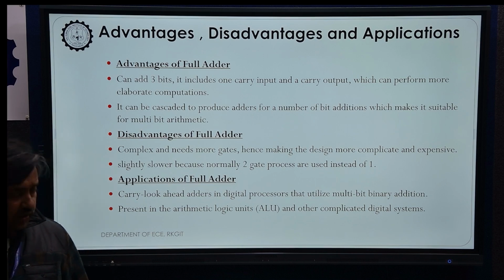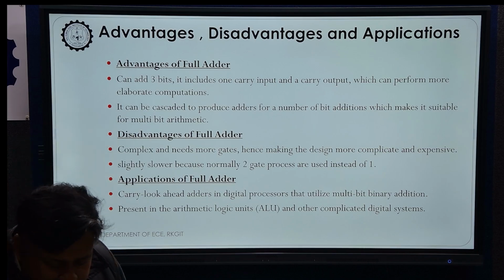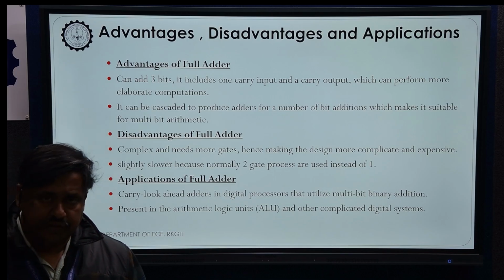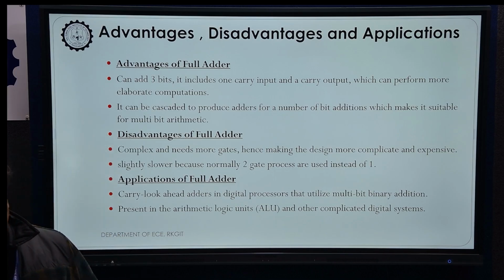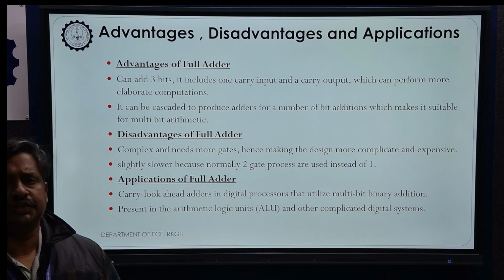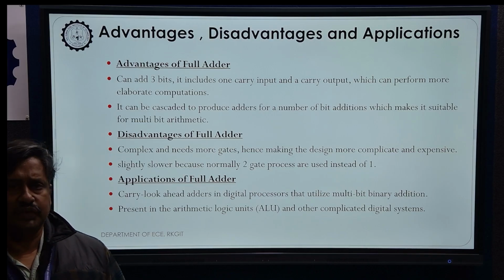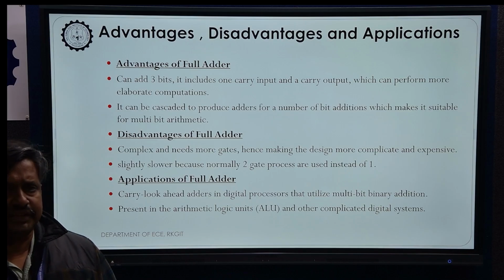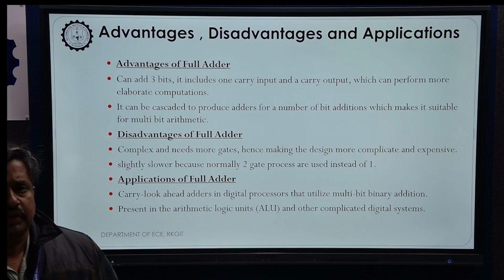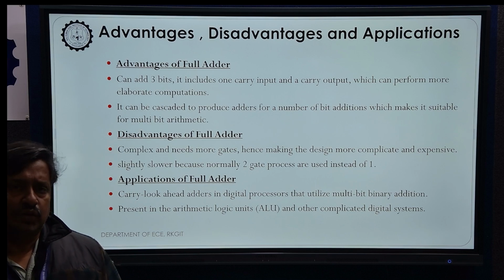So that's all about half adders and full adders. I think the half adder and full adder design is clear for you. And when it comes to combinational circuits, we have a lot of them in digital electronics. For all these digital circuits the design concept is the same: first we go for the truth table input-output relationship, then the K map, then realize the logic circuits.